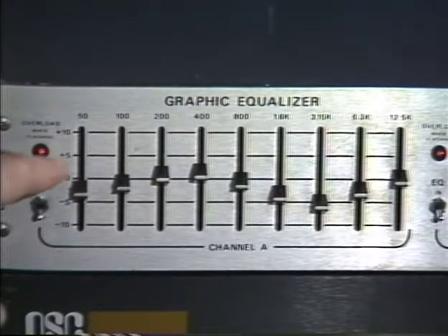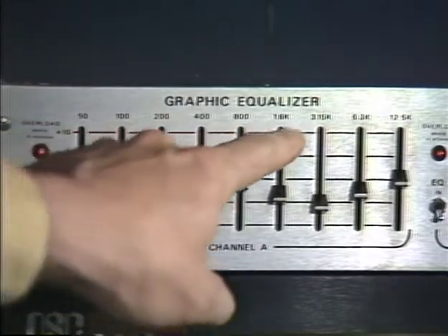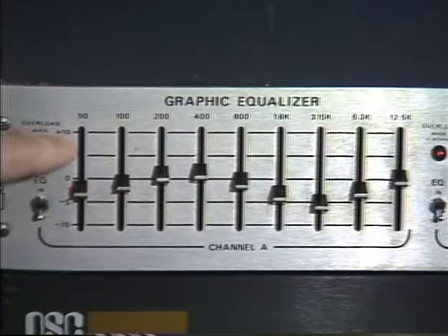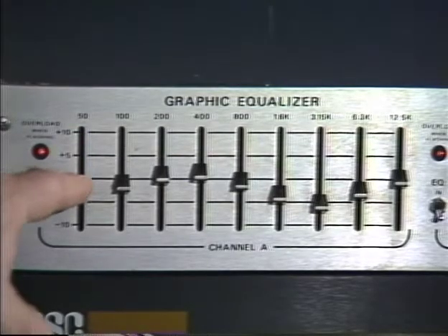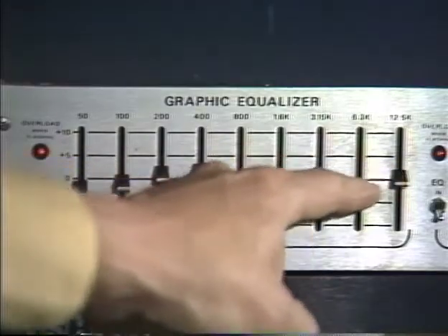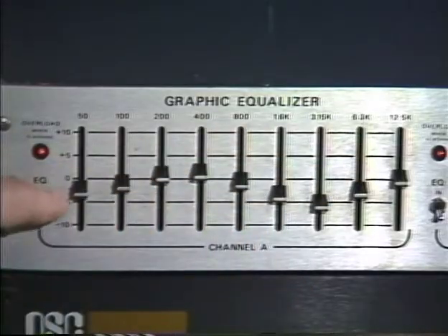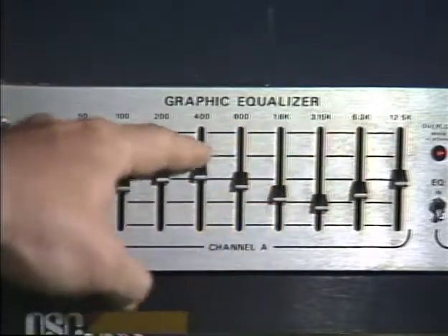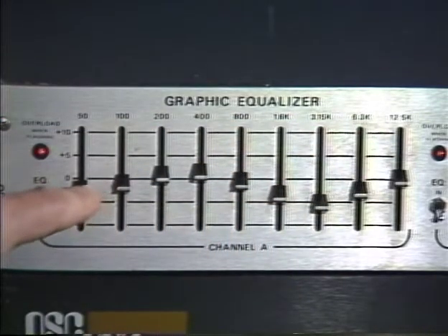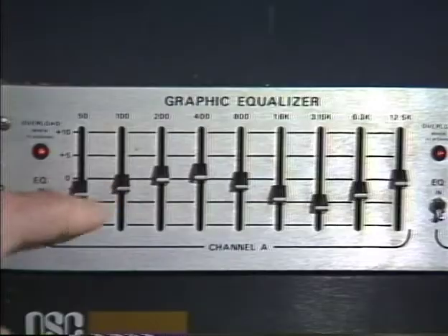What we have is a set of bandpass filters, and what's indicated up here are the center frequencies of the filters, and then a slider switch for each one that lets us attenuate or amplify, and this is a dB scale. If you look across this bank of filters, with the total output of the equalizer just being the sum of the outputs from each of these filters, interestingly, the position of the slider switches as you move across here, in effect, shows you what the frequency response of the equalizer is. So you can change the overall shaping of the filter by moving the switches up and down.